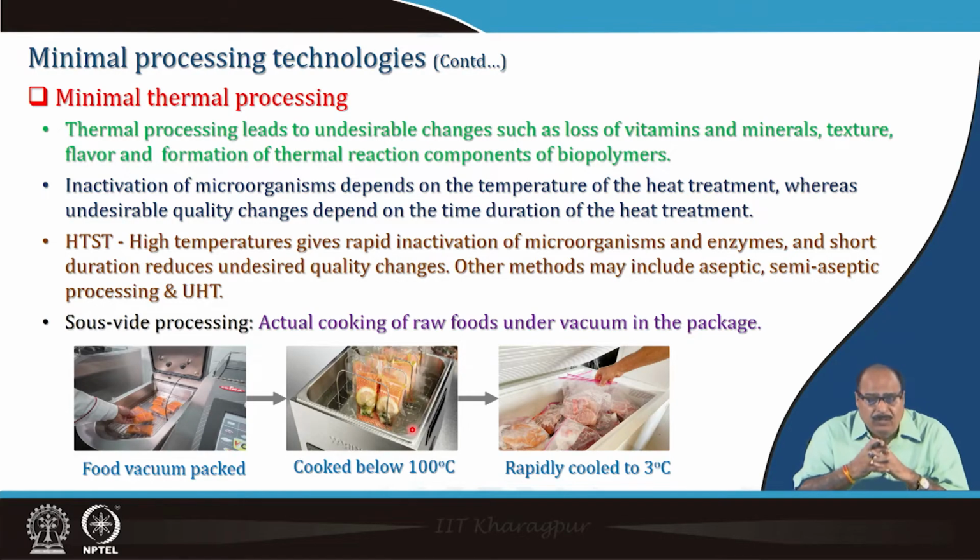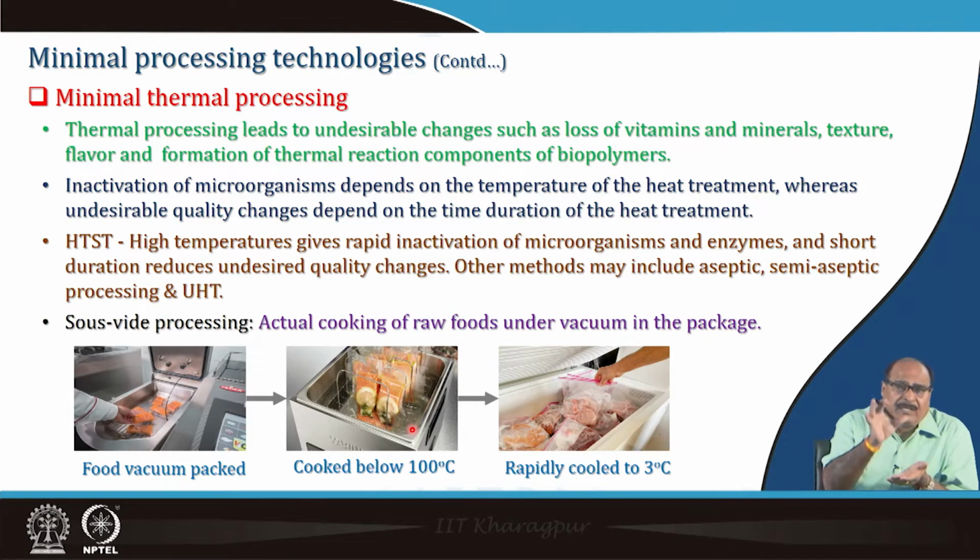Thermal processing, as you all know, leads to undesirable changes such as loss of vitamins, minerals, texture, flavor, and formation of thermal reaction components of biopolymers, etc. So, using minimal processing strategies, the traditional thermal technologies can be replaced by HTST methods, aseptic processing and packaging methods, or by sous vide processing, which is actual cooking of raw material under vacuum and then packaging, etc. So, use either traditional processes, that is HTST, particularly for sterilization, or ultra high temperature treatment.